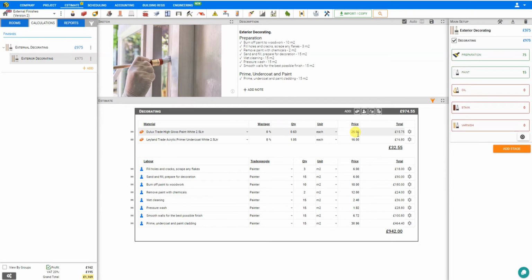Now you'll notice that Price of Job has calculated the total cost of paint based on the quantity required. This is useful if we have several jobs that may be requiring the same paint, but if this is the only job that we'll be using and we'll be buying this tub of paint specifically for this one task, we may want to increase this to the next full round number. This highlights our quantity in yellow to let us know that we have overridden the values, and we can see that our total cost for the paint has increased to 1 full can.